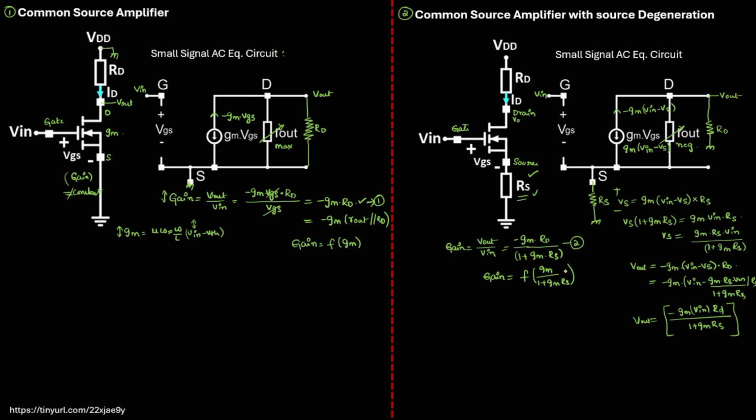So that there will be compensation, the Gm of the numerator and the denominator Gm may get compensation, so that my gain is not a strong function of the Gm itself. So my gain may be maintained, some amount of the gain maintained constant, not like the variations which we have in the first case, it won't be having that many variations with respect to changes of the V input due to the changes of the Gm also. So this is what we have to prove.